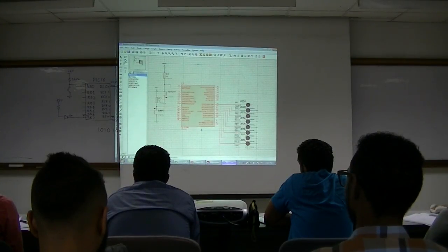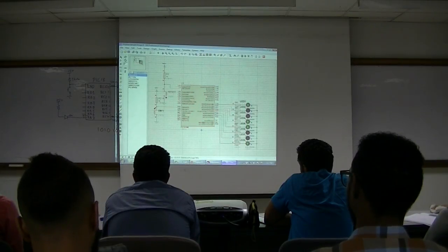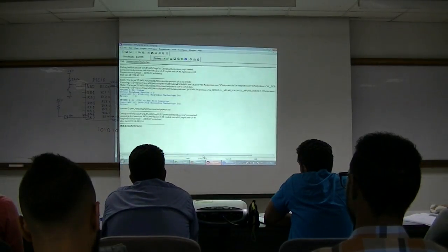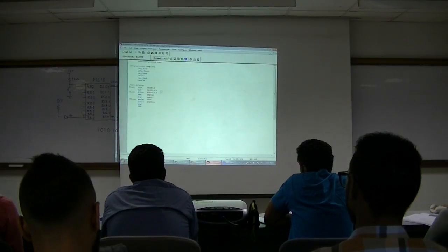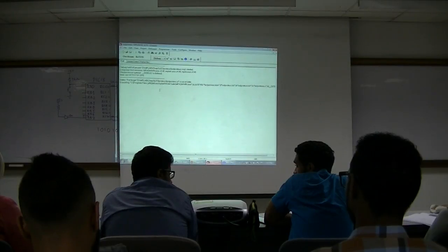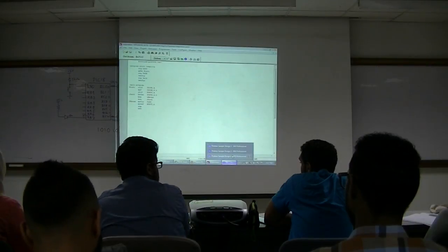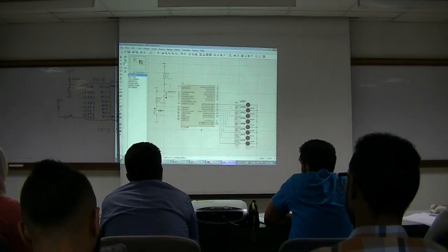Oh, I didn't do something right. What didn't I do? I didn't initialize. I didn't forcefully initialize the output port. That's why weird things happen. So we need to make sure that we initialize the port. Here, the port shift will become 0. So now, turn it on.